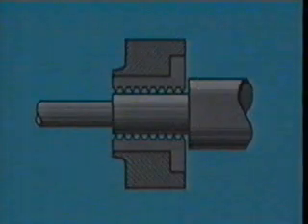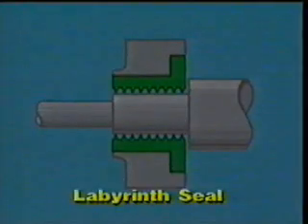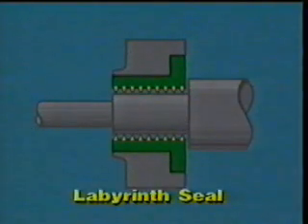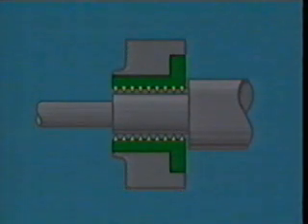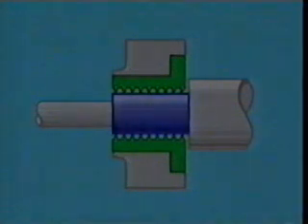The simplest type of seal is the labyrinth seal. It has a series of grooves machined to sharp knife-edge thickness that maintain a close clearance to the mating part. It can either be stationary or rotating. The mating parts are made of a softer material, such as babbitt, so they will wear before the labyrinth does. Labyrinth seals can be found in multiple, step, and interlocking configurations. Sometimes carbon rings are included with the labyrinth seal.